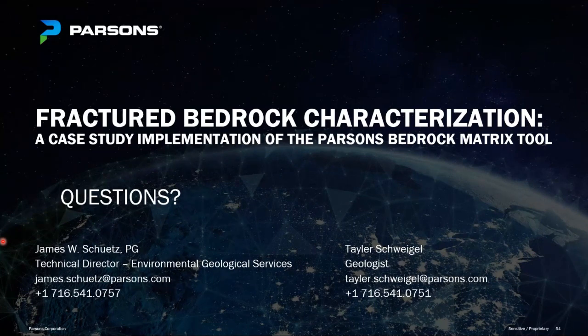And when we went to remediation, where we had to put in a lot more pilot test wells and a lot more drilling, the time it takes to core in this rock, and John, you know the same rock in Canada, is probably a factor of 10 between coring and air hammer. So eventually I just went right to air hammer, just blew down the hole, got 2 feet below the fracture.